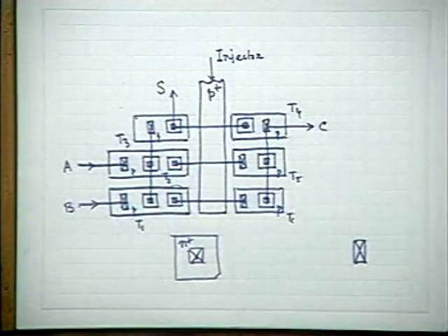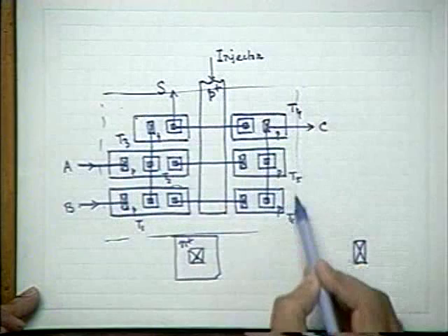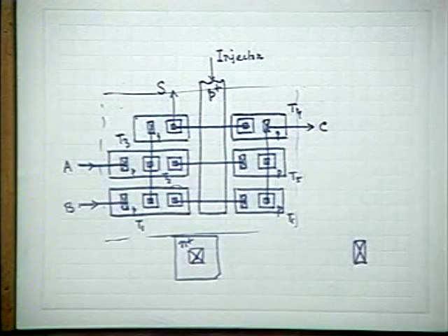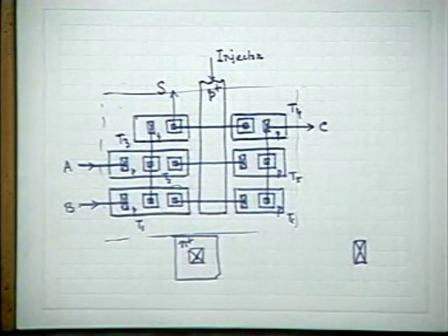That's how our aim is finally, whenever you design a chip, to implement a chip, our aim is to see that these transistors are arranged more or less in a square fashion. Ultimately, you see that I have tried to make the whole thing more or less in a region which is at least close to a square. This is called square aspect ratio. The chip is not usually a thin rectangle. It is usually a square, or sometimes X and Y may be a little bit different, but not much. So I have to place the transistors in such a way while doing the layout that the overall aspect is almost a square.